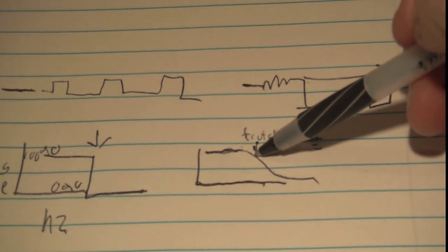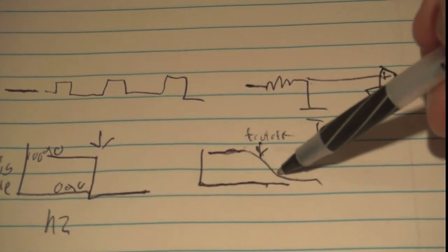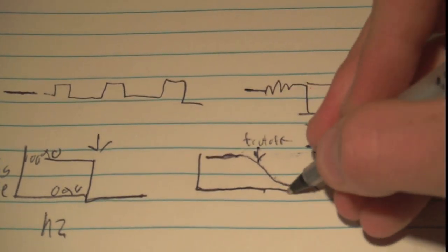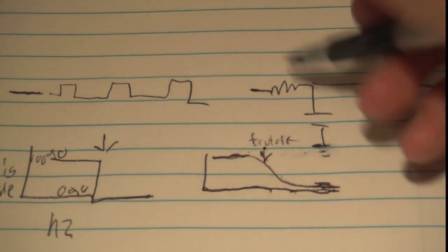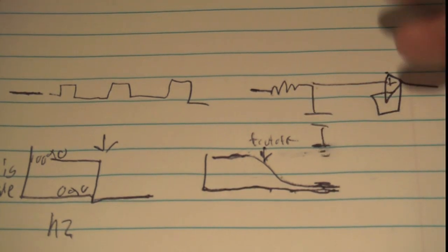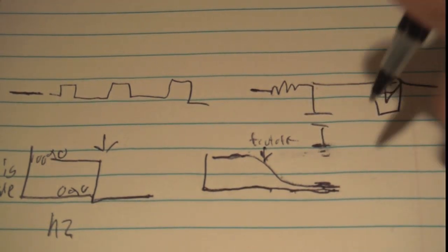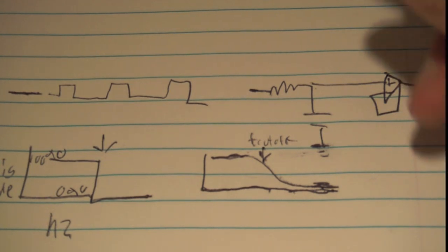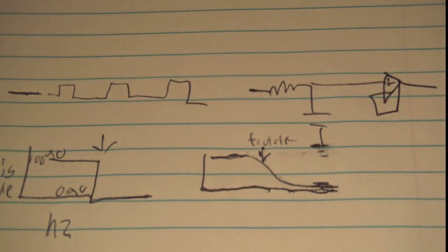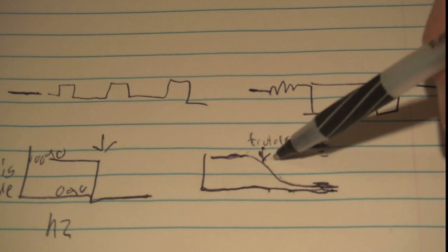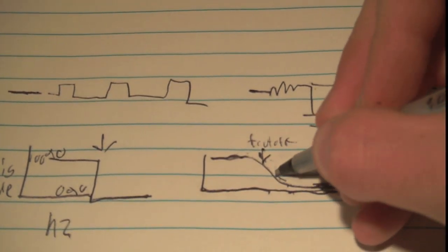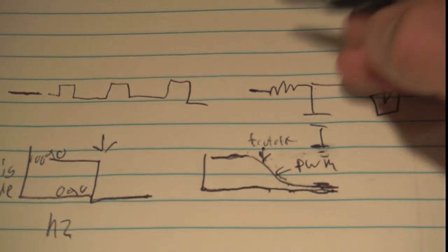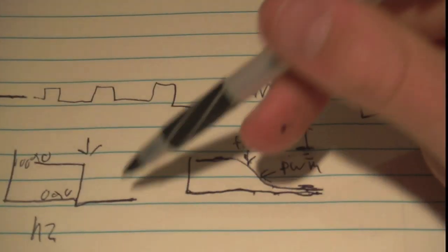Then after our cutoff frequency, slowly and pretty linearly, we're going to start attenuating it, and it's going to get real close to zero. But it's never going to actually 100% attenuate anything, because there's no such thing as a perfect thing in electronics. So a higher frequency of our PWM will still make it through. Say our PWM frequency could be right here. It'll get mostly attenuated, but it won't pass through.